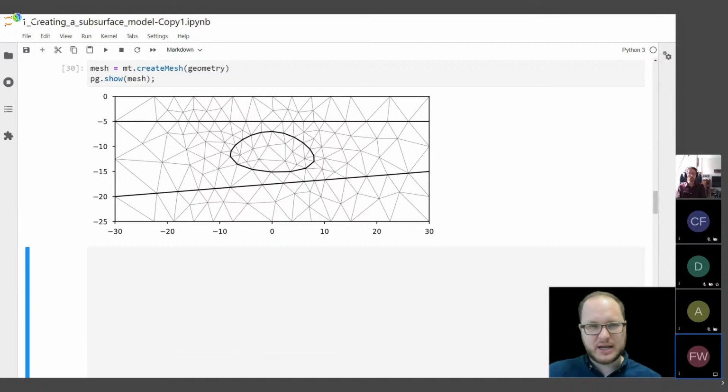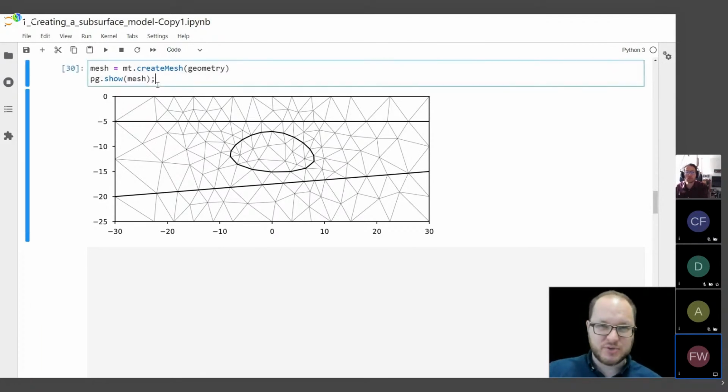If we want to do finite element simulations with this later, then we also need to be aware of mesh quality. So we want to avoid sharp edges. So we need a high quality mesh also for high numerical accuracy. And also when we do an inversion, we also have to be aware of our mesh, because each triangle would represent a subsurface parameter, and we want these parameters to be according to the resolution of our method.